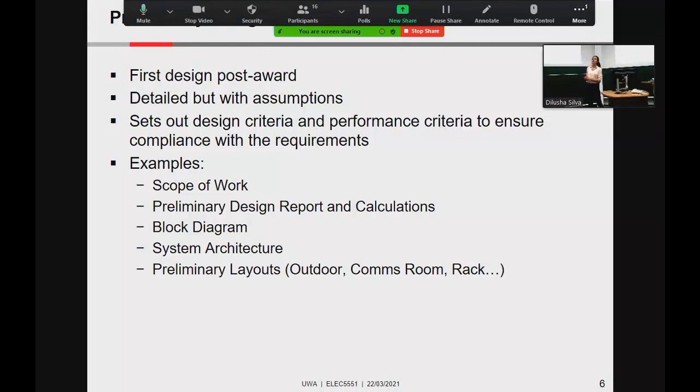They cannot share. None of the signaling cables could be used for, say, the operations network. So all of these scattered requirements here and there, we gather all of these, and the conclusion is we can fulfill all the requirements with 4 separate fiber cables of 12 core fibers. That's our design criteria, step 1.